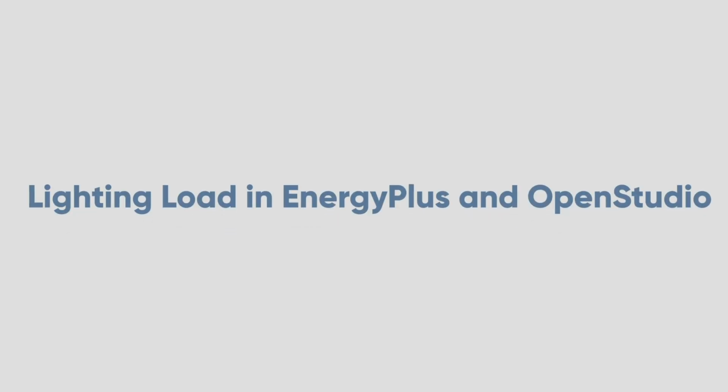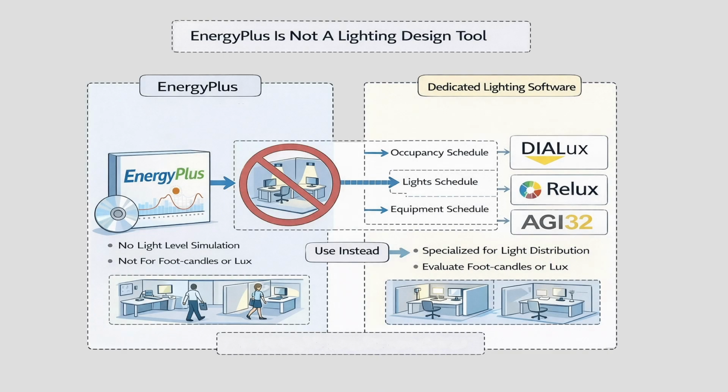Let's talk about how lighting loads are handled in EnergyPlus, and therefore in OpenStudio, because there are a few important things to understand. First important point. EnergyPlus is not a lighting design tool. It doesn't simulate light distribution across a room. It can't tell you whether your luminaires provide enough foot-candles or lux on the work plane. That job belongs to dedicated lighting software, like DIALux or Relux.